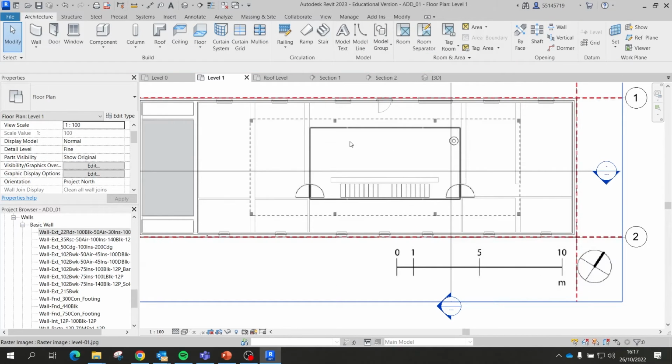And I'm going to create now the glass box. In order to create a glass box, since I want to use it to attach the roof, the first thing that I do, I create a glass box that is not sitting exactly where it should. So I'll have my glass box, which is gonna be made of a curtain system, right, running all around where the roof line is.